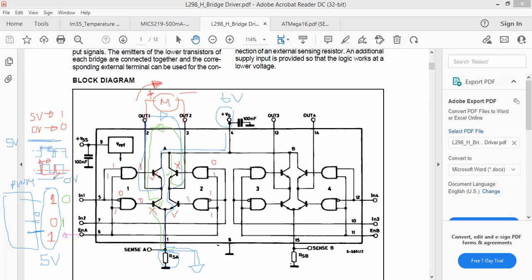And if you want to run at the lowest speed, like 0 RPM, you can set the PWM duty ratio to 0. So the motor will be turned off. In between, by adjusting this duty ratio, you can achieve any speed that is required. That is what we call PWM. So the speed and direction can be adjusted by using this.